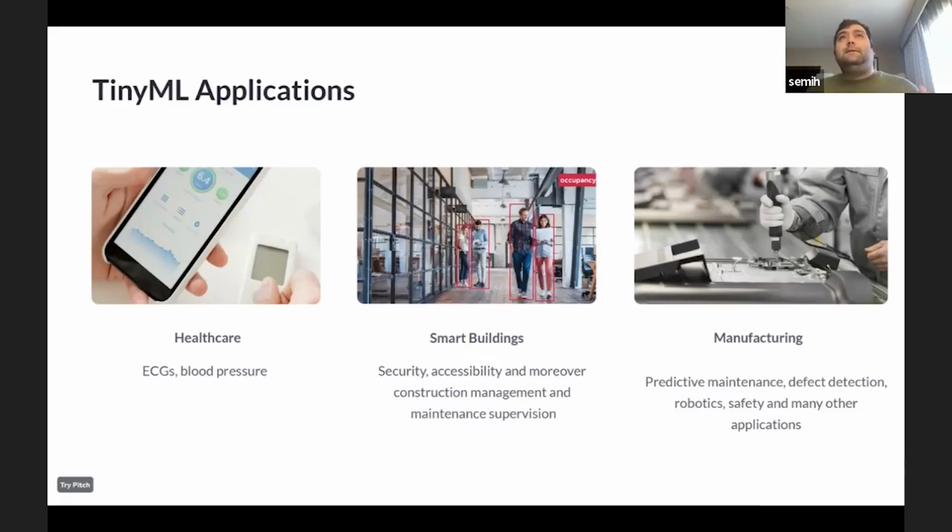In the quality assurance laboratories that we worked with before, we had refrigerating systems to follow and measure. You can try to upload the data to your cloud systems and run how the cooling systems are working over time and detect if the cooling is working as expected or if there is a defect. You can pretty much do that in the lab environment. That works fine, but you need to really adjust the compressor to work in whatever environment the refrigerator is going to be in. And that is one of the applications of TinyML: you have this initial model, then deploy it in the fridge, and it keeps potentially adjusting in that new environment where you don't have the lab conditions, with different humidity and temperature, and you just follow up in that environment.